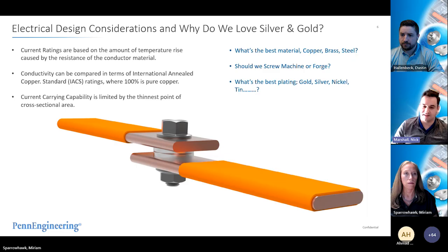And the eConnect contact bushing is designed to work in both copper and aluminum bus bars. And because it's such a small piece of the total bus bar, we've made it out of a copper alloy that gives you very high current carrying capability and is able to be installed into the aluminum bus bars. So you get that really good joint resistance at the terminal while you get the cost and weight savings for the aluminum bus bars.